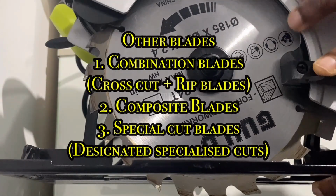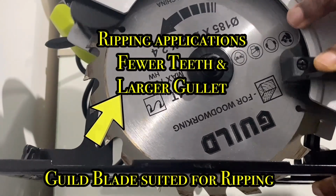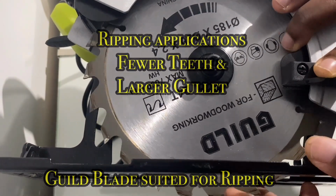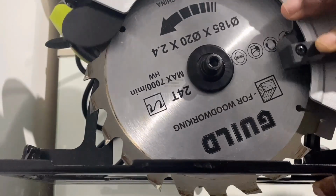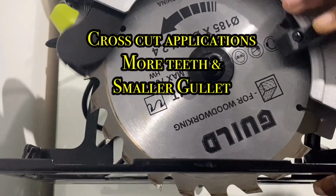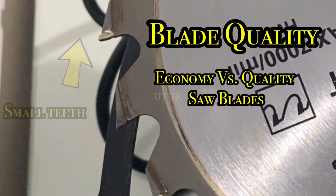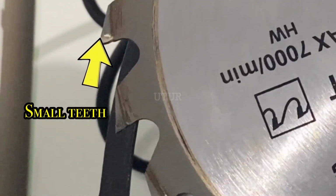In general, if a saw blade has fewer teeth, the speed rate will be faster and it will have a larger gullet size. And larger gullet sizes are most suited to ripping applications. But if you've got more teeth and smaller gullet sizes, then it's more suited to cross-cut applications. I'll show you what I mean in a minute, okay?